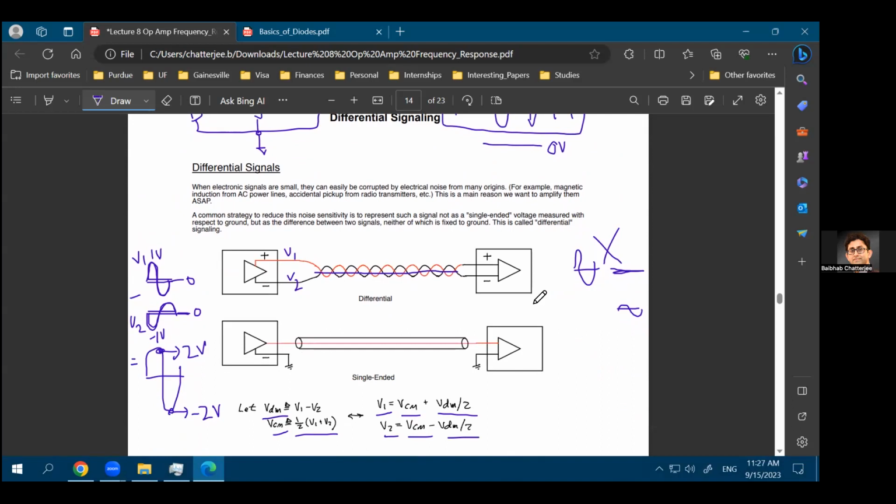So let's say you are designing a circuit in the range of 100 megahertz, and you know that the FM frequency is between 88 to 108 megahertz. That's why you have your FM radio. So if you're designing your circuit on the breadboard or on a PCB at 100 megahertz, and you always have interference from FM, whenever you're trying to amplify your original signal, it's also trying to amplify the FM signal that is present in the environment. Right? So that is an interference, and that is hurting your implementation of the amplifier.